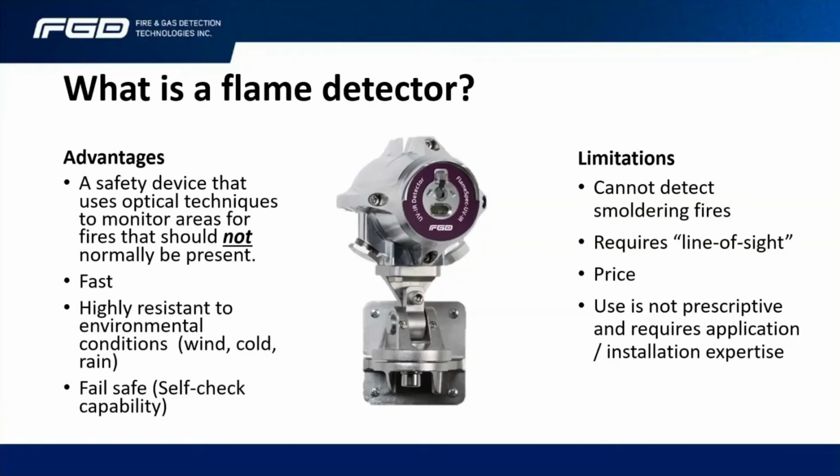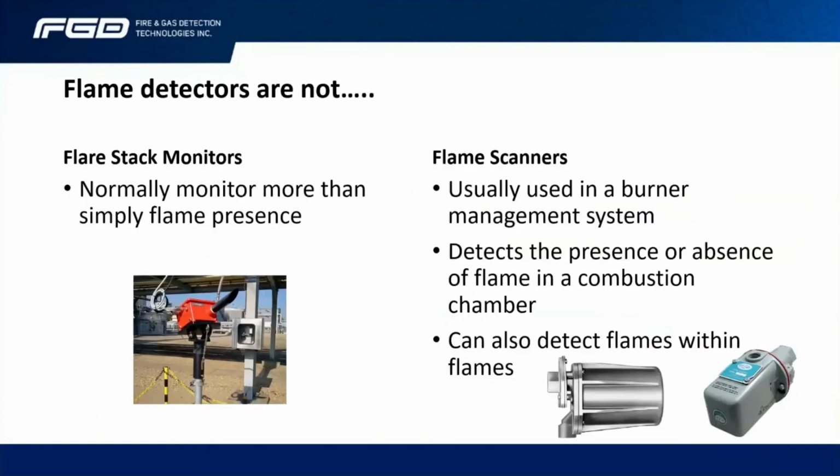The other thing that's quite interesting is, unlike smoke and heat detection, there is very little in the way of prescription within standards for the implementation of optical flame detectors. It usually comes down to good engineering practice based on a unique application, perhaps a petrochemical plant. So it's real engineering expertise and design that's needed. Flame detectors, in understanding what they are, it's very important that we understand also what they're not.